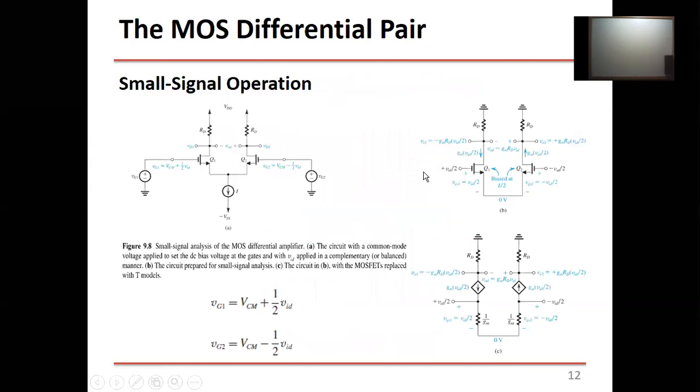Then we started to talk about the small signal. So this was the large signal, the DC analysis, okay? Again, you need to distinguish between the DC analysis and how we treat the circuit in DC analysis, and the AC analysis or the small signal operation. These are two different approaches, okay? In DC analysis, we keep the transistor, we assume the signals are large, so we don't replace the transistor with this model, we just use the KCL, KVL, and these analysis techniques.